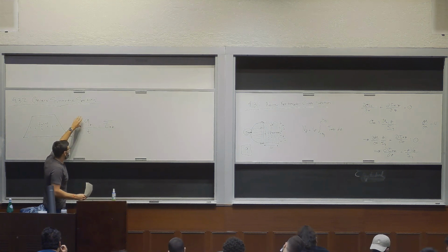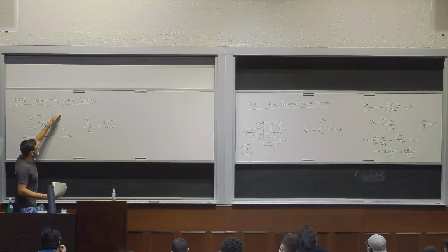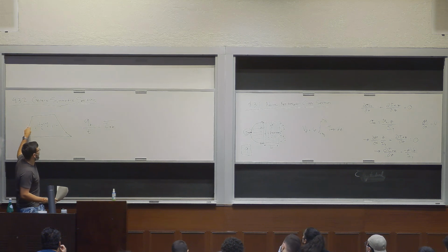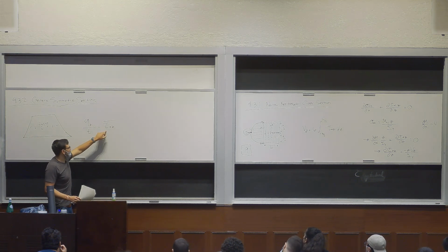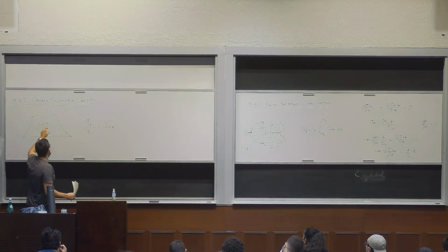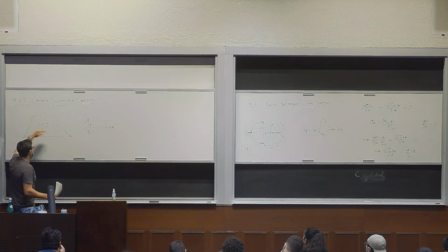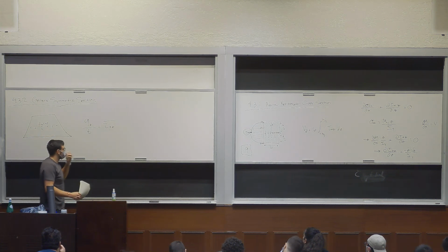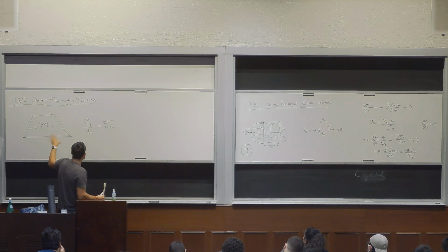Whenever we solve for Q, if we divide that Q at any given Z position by the thickness at that location, we'll get the average tau xz. We might not get the exact tau xz at any specific location, but we'll get the average. And that's still valuable. Just keep in mind that if the distribution is not uniform, then we're solving for this average.